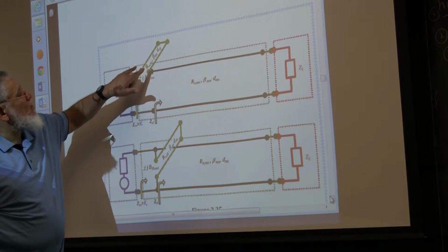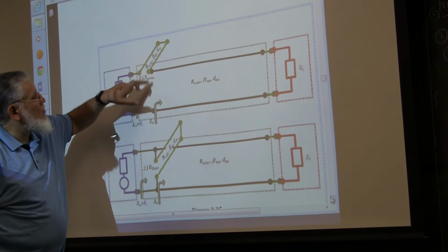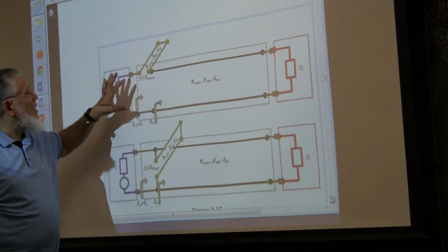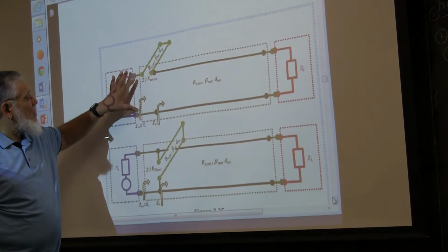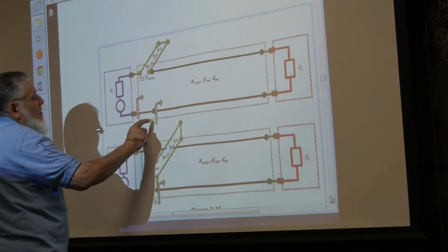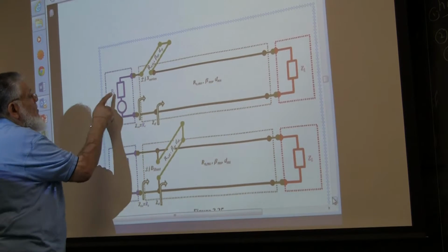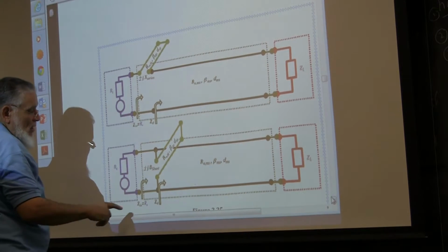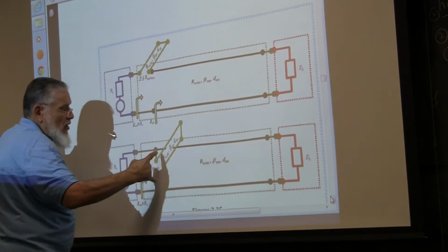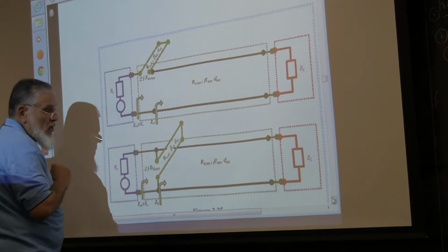So you add another transmission line like that, and the combination of the location that I chose on my line and the length of this, the combination of these two can get me a good matching right here. So if you have a ZL here, you reach a level here where you have a certain characteristic impedance, you add that reactance, the combination becomes your Z input equal to RS, so it's matched to your source impedance. Same thing here. You move down the line, your ZL and Z of Z changes until it comes to a certain characteristic here, and when you add that reactance, you end up with, again, Z input equal to R sub S.